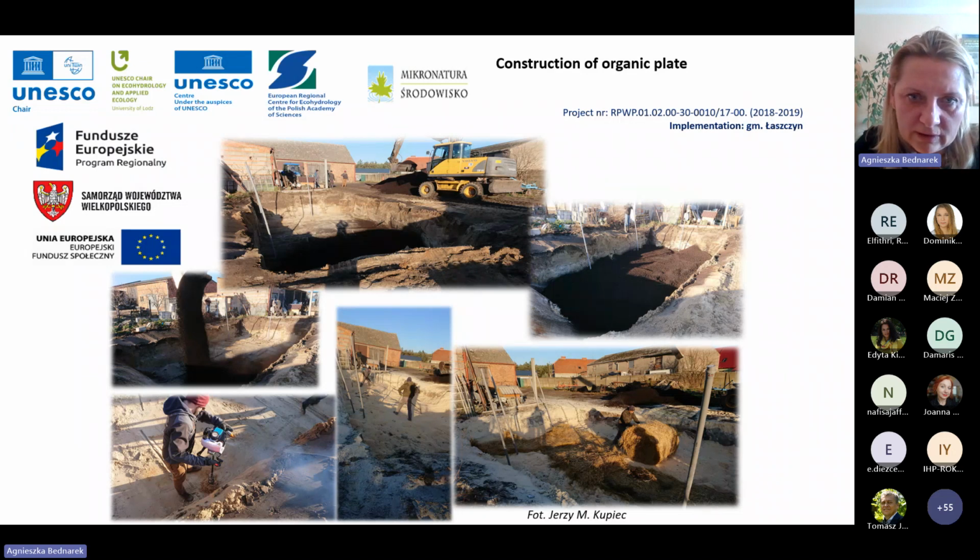Here is also an example from one of the projects in a bigger farm. We built much deeper denitrification beds under the place where the farmer collects the manure from the pig farm. We built them using brown coal, straw, and pinus sawdust, and we mixed this material without any geofibrous boxes, without any modules. We just put this in a hole in the ground. Then, after preparing this system, the farmers collect the manure in this place, and during this project we monitored the effectiveness of this barrier down to the deepest meter.